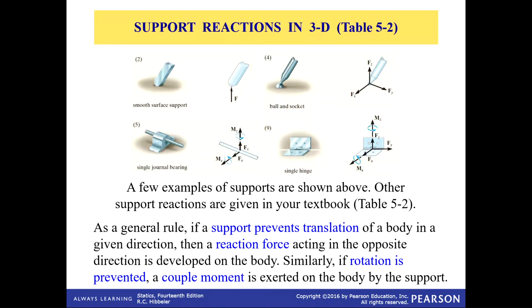The journal bearing. So with a journal bearing, that shaft can actually slide through the bearing. Typically there's some kind of mechanical stop put on there so that doesn't happen, because obviously you wouldn't want that to happen in a real system, but it can slide through. So it can spin, of course, because it's a bearing, it's supposed to spin. It can slide through. However, in the other two directions, you better not be able to move it in those other two directions or spin it in those other two directions, or something is seriously wrong with your bearing.